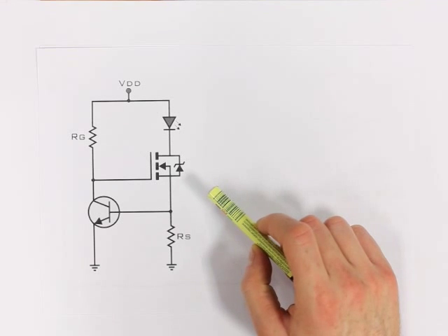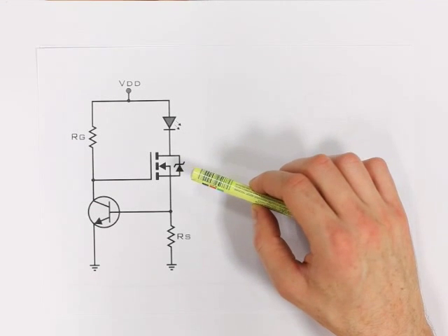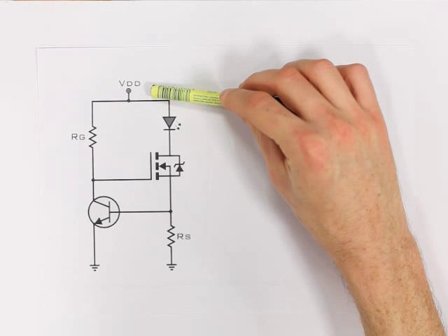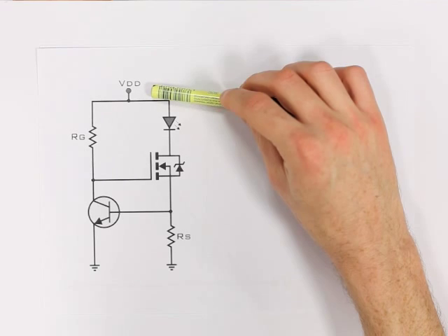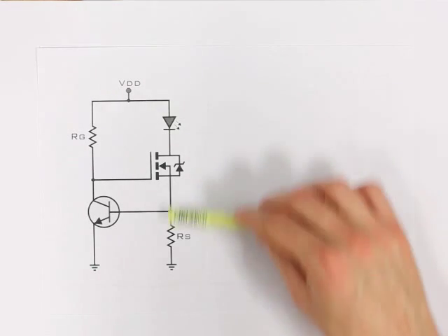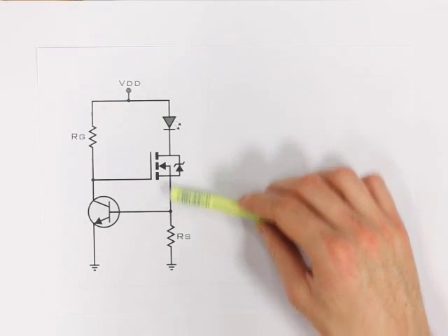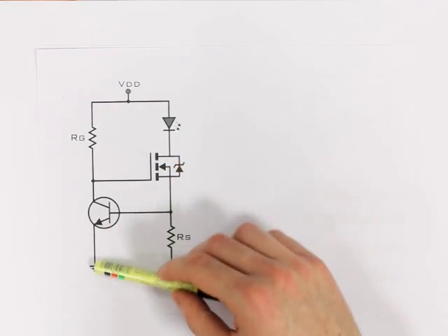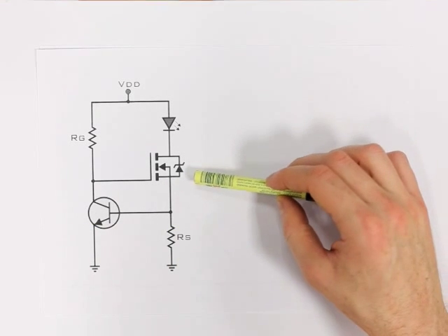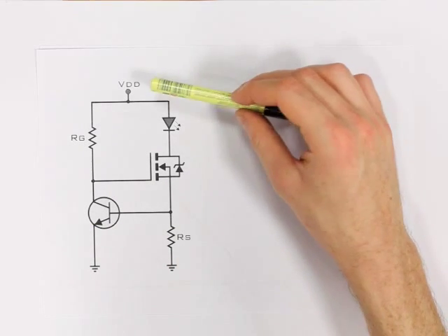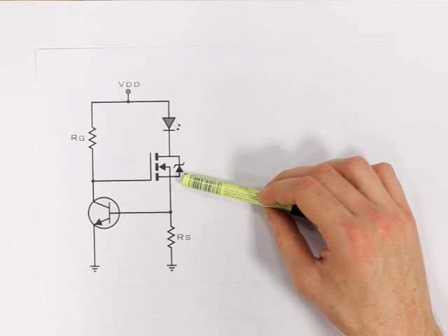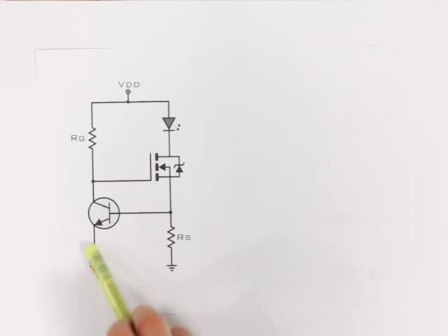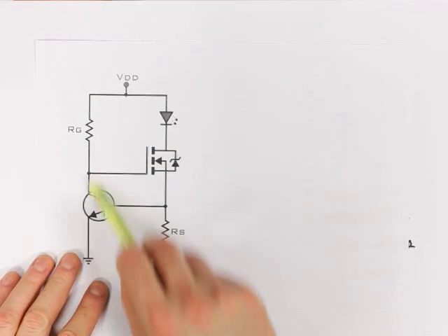So power consumption here is actually very simple to calculate. All we need to do is multiply the source voltage by the current drawn from it. And the current drawn is just our selected forward current, same as the series resistor circuit, plus a tiny amount for the MOSFET control branch down here. So even if we pretended that we had the same supply voltage as with the series resistor circuit, this one would consume slightly more power due to the less than 1 milliamp that we're getting down this branch.